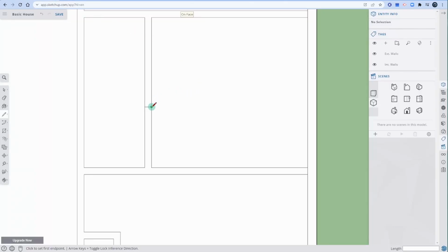So I need to be able to fit a bathtub. So it's actually from this side. So let's draw this line all the way across. And then from here over, I'm going to type in 60, hit enter. Where's that line? There it is. Just bring it down. This line over, 4.5, enter. There I am. Bring it down. And this wall is from here down. There it is, 4.5. Bring it over. Spacebar to get to normal mouse pointer.